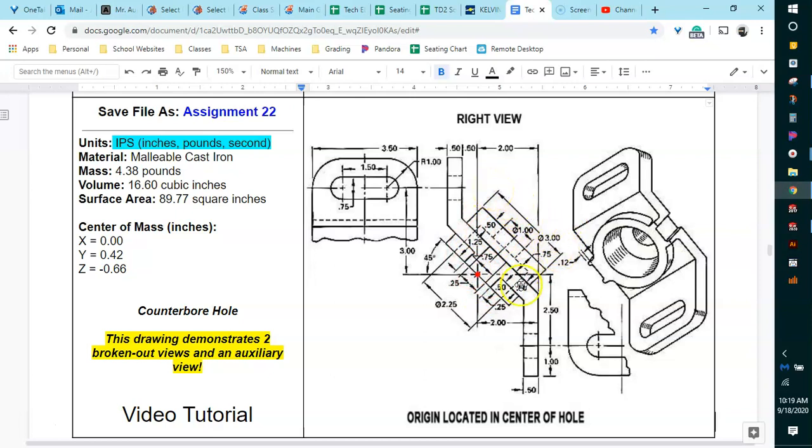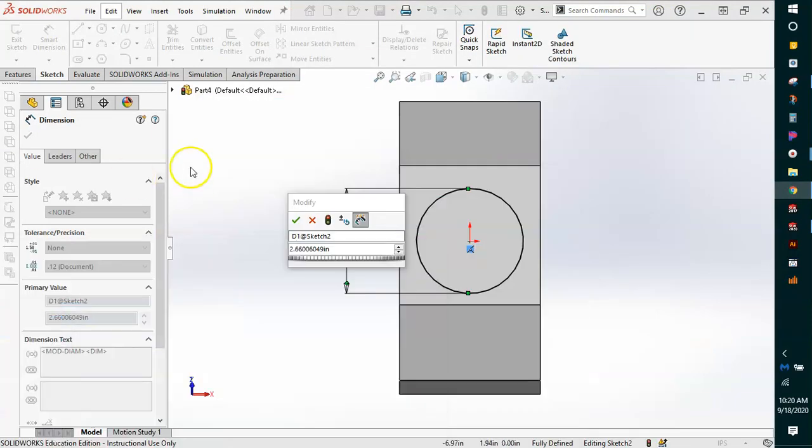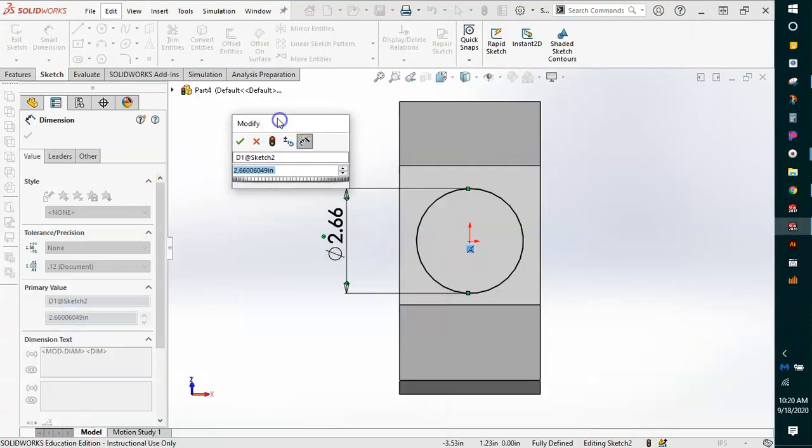And then when we extrude, since we're only on this face right here, keep in mind there's some that comes forward and some that goes out the back. Well, what comes forward we already know is 0.5. What goes out the back, it says that it has a measurement right here, which is tough to see, is 0.75. Now, you can't just say 0.5 and 0.75 because we also have the thickness of this material. So coming forward is 0.5, going out the back is 0.5 plus 0.75. If you think in terms of change, 50 cents plus 75 cents, we have $1.25.